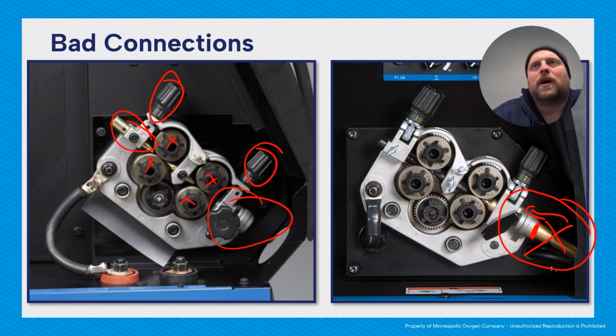So, I had somebody who said, hey, getting porosity, don't know what to do, and I kind of walked them through verbally what I've shown you. And they're like, no. And I'm like, well, bring it in, I'll take a look at it. So they brought it in, I popped open the cover and I looked, and that's what it was, it wasn't seated properly. So you have the screw, you go ahead and unscrew it, you go ahead and seat it, push it in, screw it down, good to go. So that's a major thing to pay attention to.